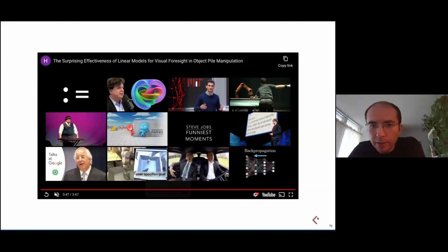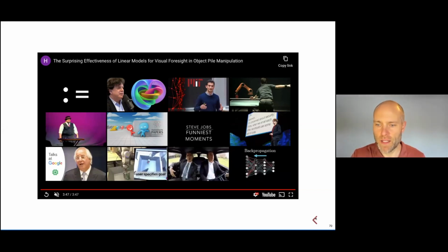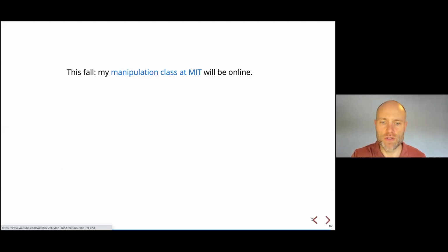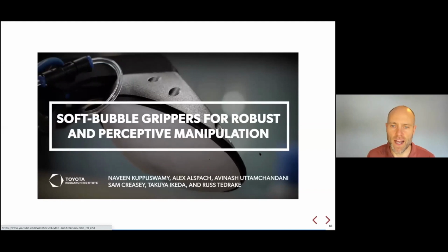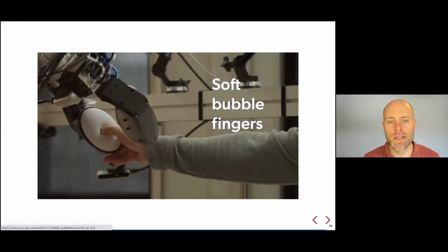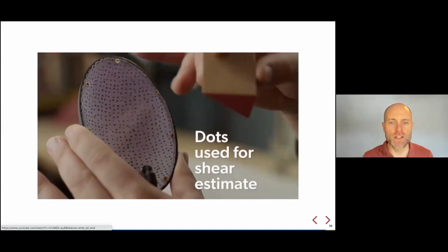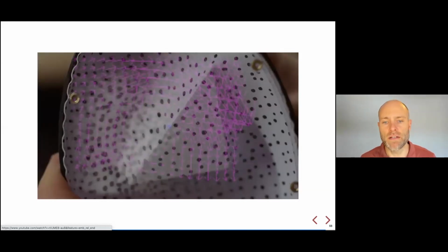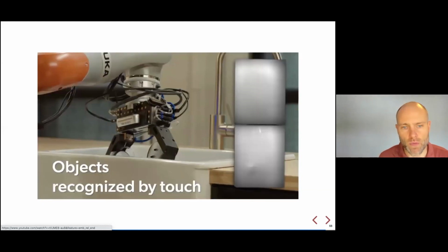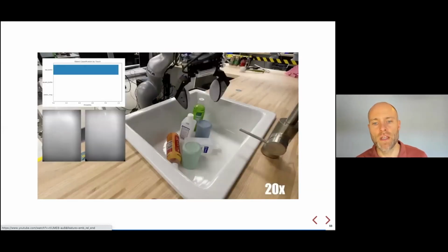Great. So Philippe Nadeau asks, tactile sensors can provide very precise local information about contacts. Are current optimization algorithms able to deal with the quantity of information involved by the skin of an artificial hand? That's what the last video shows. I'll play it while I answer, but we have some videos of dense geometry sensors that we've been building at TRI, which combine two ideas. One is the mechanics of the interface changing, and that it's better to have surface patch contacts and compliance than to have point rigid contacts, even though they're today harder to think about. And then you can do this dense sensing and rich slip detection, rich force detection, and the like.